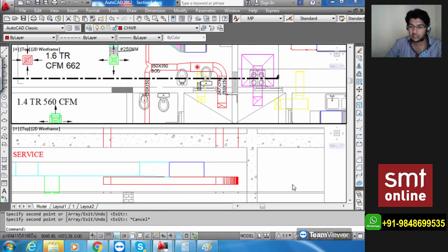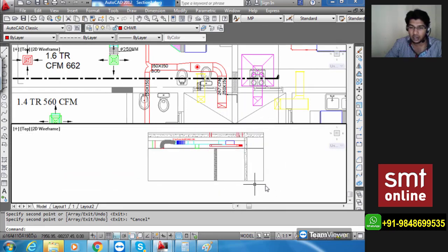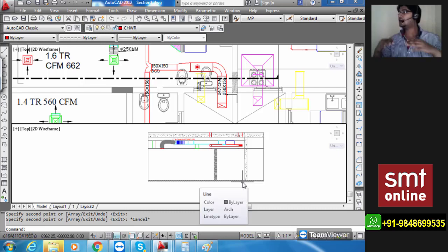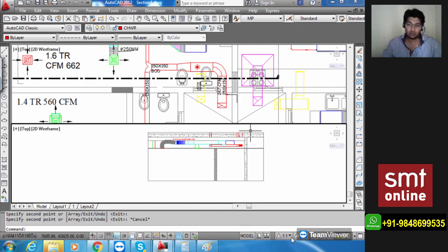Lastly, what is left inside this room, that is inside this area, we have a kitchen hood. Now for creating the kitchen hood you need to have a platform where you're going to stand up to some height to do the cooking. So as per the thumb rule and as per the designing estimation standards, we have that limited to at least 700 mm. You will be getting in your kitchen ventilation systems how to do the kitchen hood design and so on. So we first need to create a platform of up to 700 mm. 700 mm is how much in feet? Just a little more than 2 feet. 2 feet 4 inches, you can say.